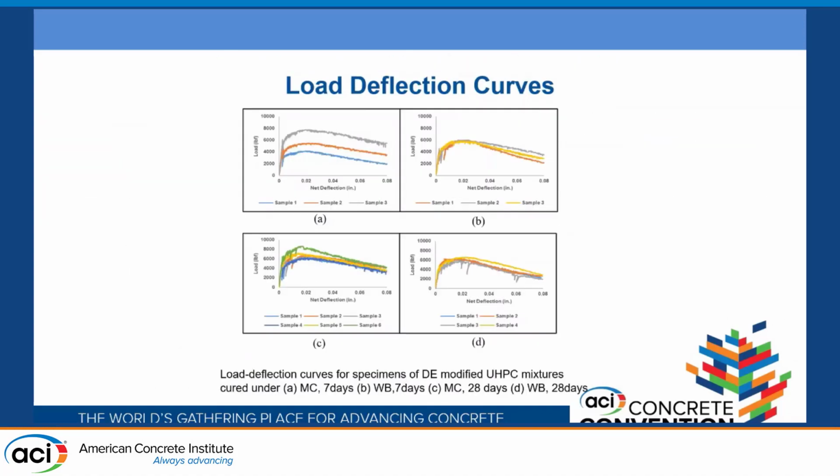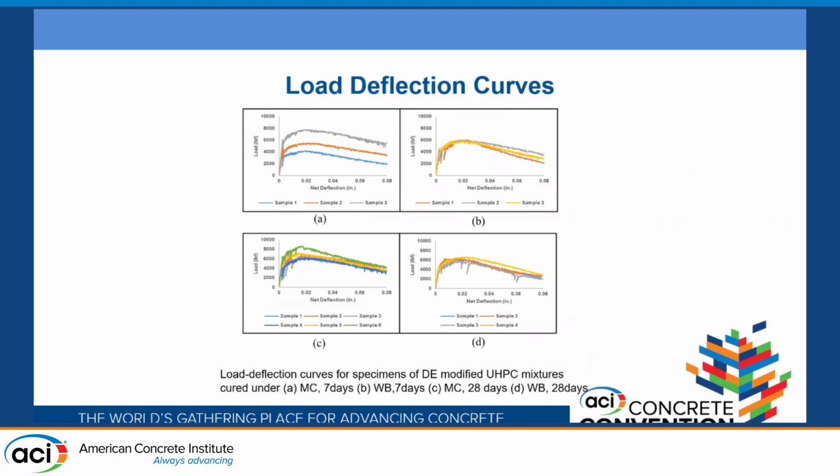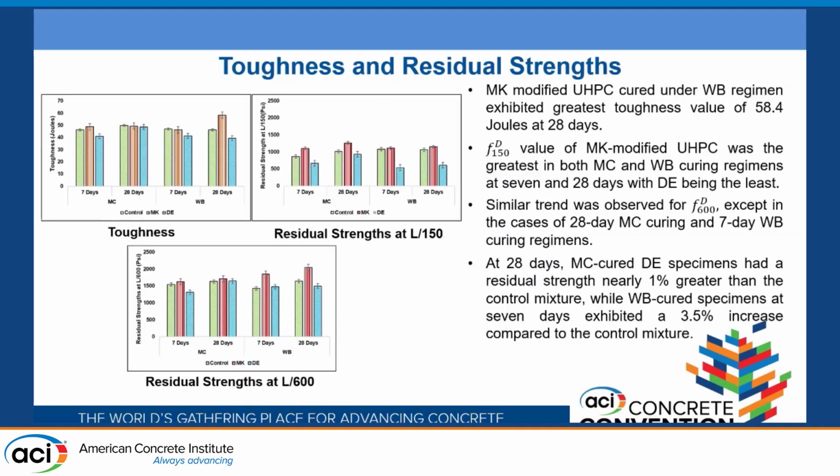These are the load deflection curves which I have used to calculate the MOR, peak, toughness and residual strengths at L/150 and L/600. The highest toughness value was exhibited by the MK mixture at 28 days when cured under WB,